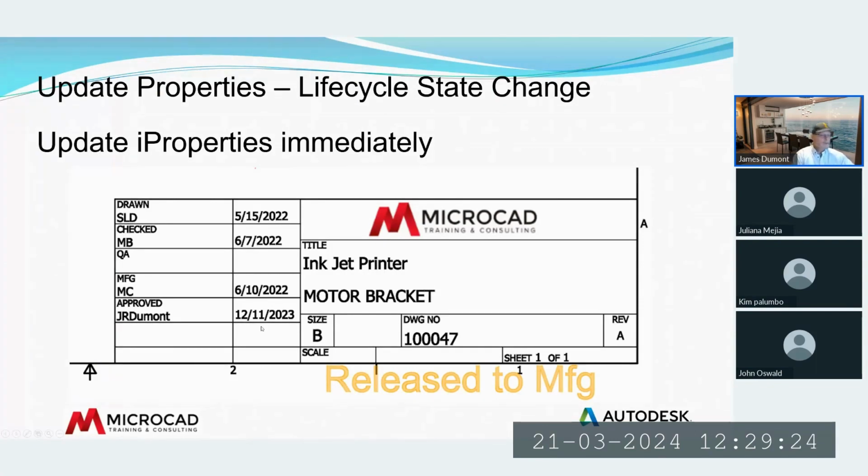They're no longer valid. If I change it from release to WIP, it has to go through all new signatures again. So one of the things we can do, and most people don't do this because it takes time and energy. They kind of circumvent and try to get around this. But using the Power Jobs, if I change the state of a file, it can automatically do things for me. And one of those things is clear these properties.